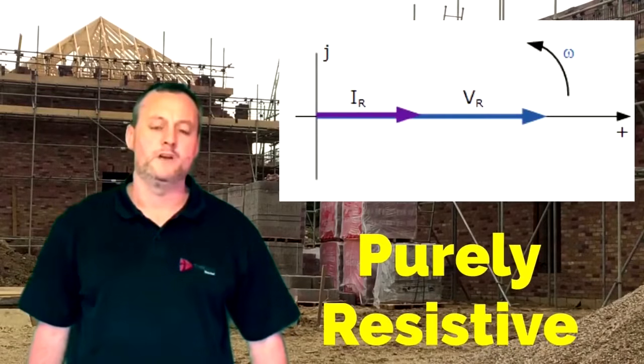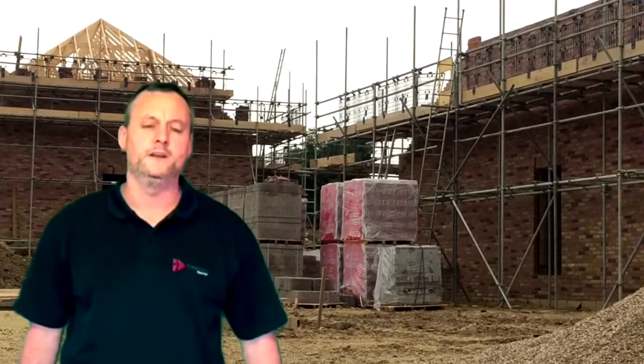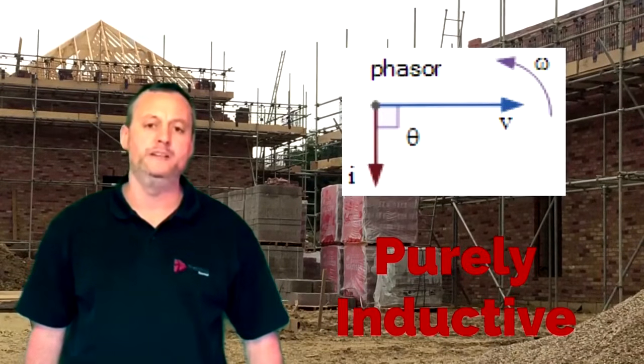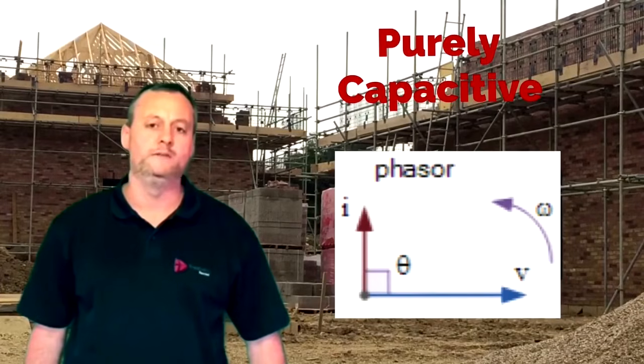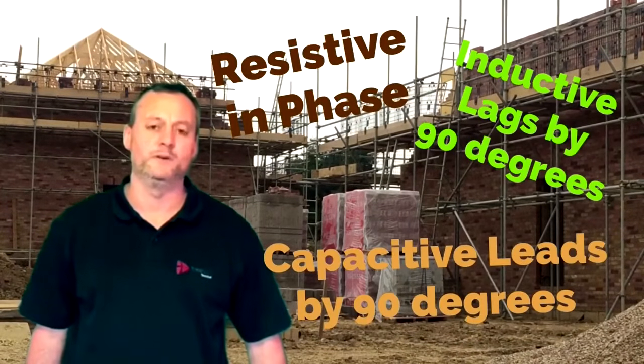We said in an AC circuit that is purely resistive, the current and voltage are in phase. We said in an AC circuit that is purely inductive, the current will lag the voltage by 90 degrees. And finally, in a purely capacitive AC circuit, we said the current will lead the voltage by 90 degrees. These 3 are regularly asked in multi-choice questions, especially at level 2, and need remembering. Resistive in phase, inductive lags by 90 degrees, capacitive leads by 90 degrees.